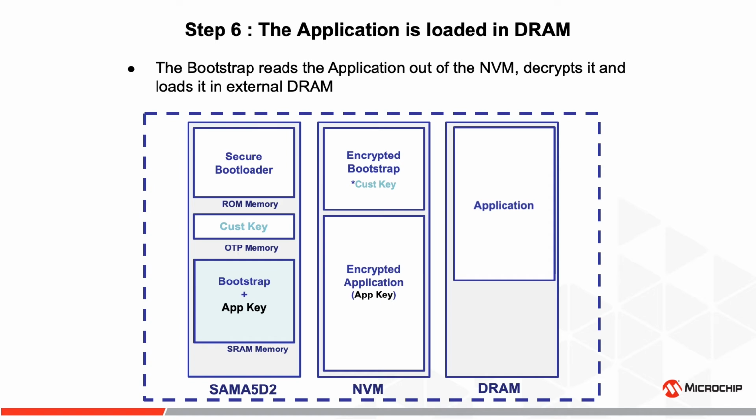In this particular case, we show the application as being both the OS loader, the OS, and the end user application. This process can be repeated many times. So if you want individual encryption for the individual aspects of the product, i.e. you want a different encryption for the OS versus the application, this is all provided through the secure boot provisioning with the secure SAM-BA application. Again, like I mentioned before, this would be repeated if we were to have independent encryptions for the different applications.